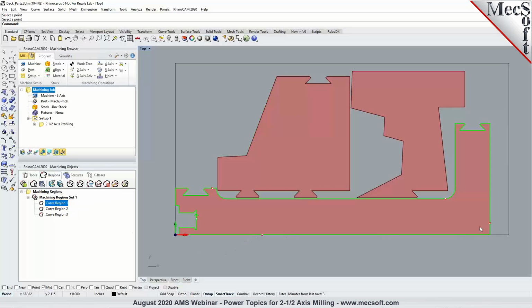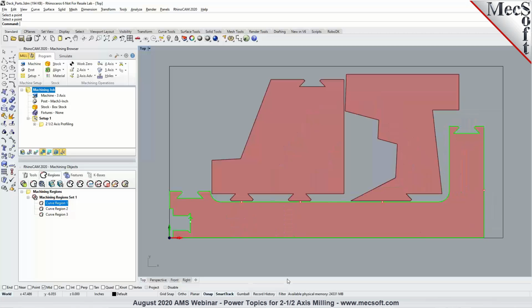And once you create the bridge points, you could also move the bridge points. I can just double click, or I can single click on it and move each of the bridge points. I could say I would like to take this bridge point in here and move it closer to this location. Now, rather than having to click on it each time, I can use it in a modal setting, double click to edit so it stays modal, and I can keep moving multiple bridge points in here. I can take this one here and move it right over here. And then once I've done moving the bridge points, I can right click or press enter to accept it.